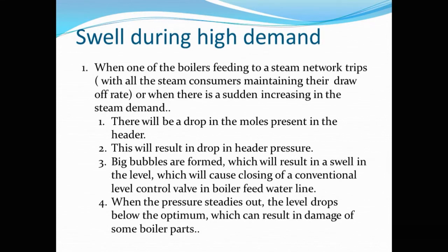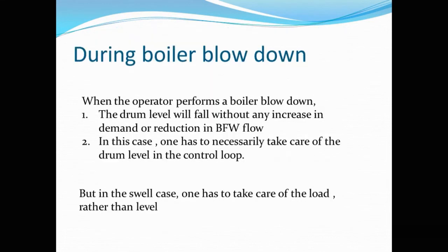So there is a sudden swelling of the water level because of aggressive boiling, and this will be wrongly sensed by the level controller, which will try to close the boiler feed water valve. The system regains the original situation after some time, but we find that the level in the drum has gone very low. This will result in major damage to some of the equipment.